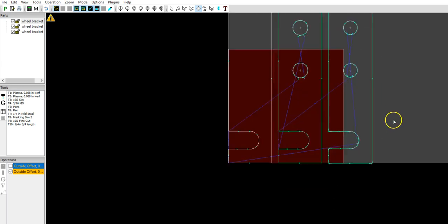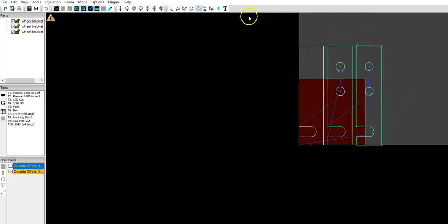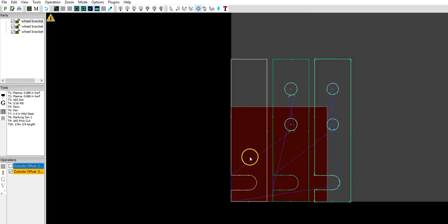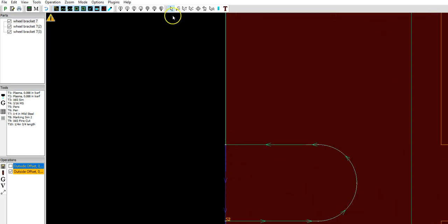So there you have it. Completing shapes ensures that we actually have proper cut paths made. Yes, it may look correct, but that doesn't mean that it's going to cut correctly. You may lose anywhere from a 1/16 to an 1/8 of an inch off of a cut by not doing this correctly. So make sure you double check your files, make sure that you don't have,